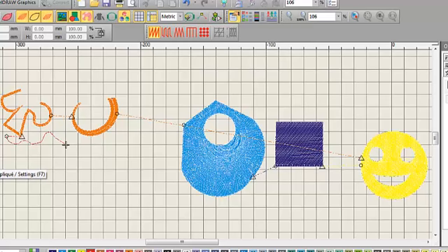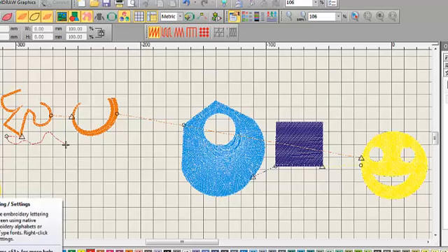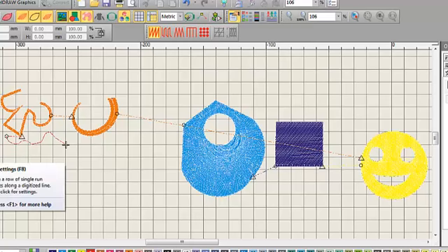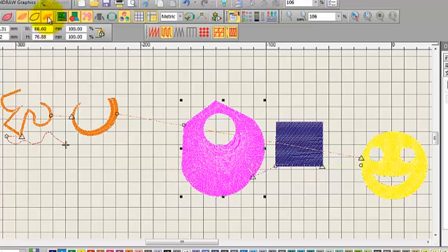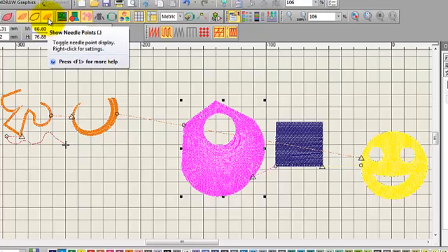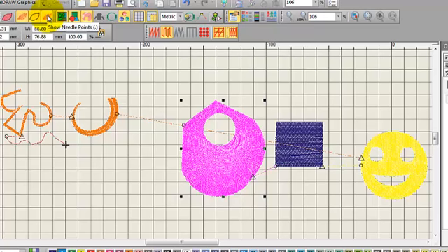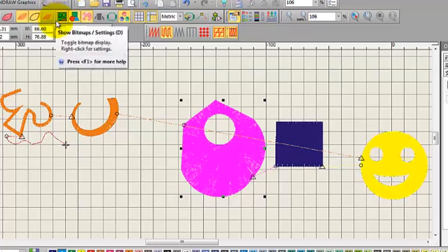Look, we might leave the applique and the font tool for another session, but it's quite simple. Your stitch types, your digitizing tools, the different ways you can view objects. We haven't had a very good look at that. We've looked at the stitch points and you can see them displayed there. I'll turn them off again, and the shortcut for that is the full stop or the period button. So I'll hit that on the keyboard and the stitch points will disappear.